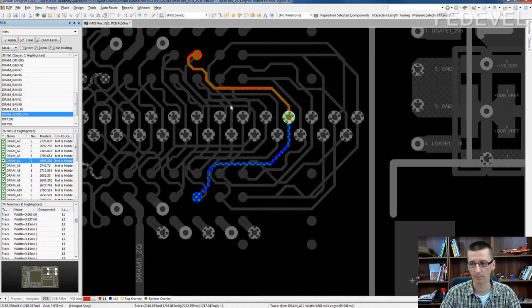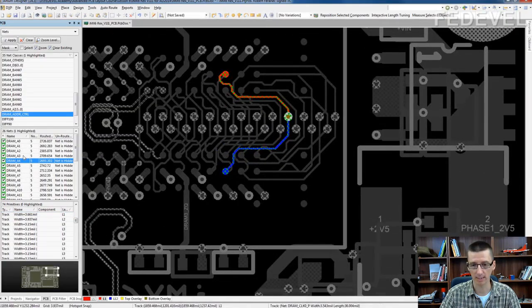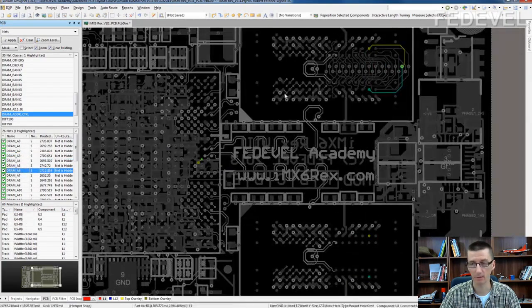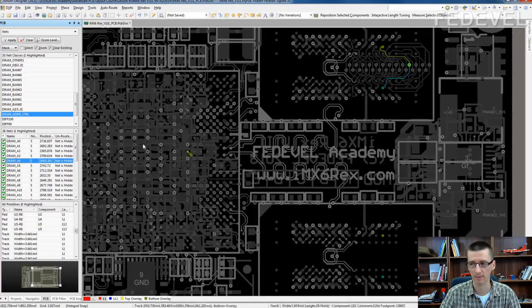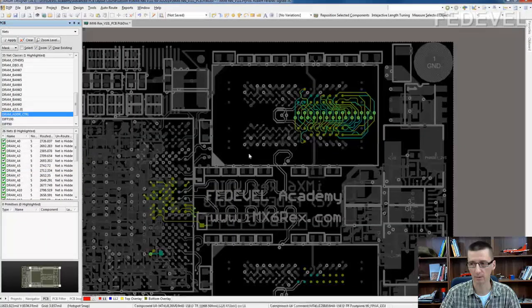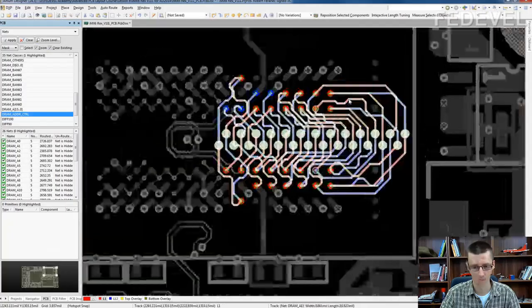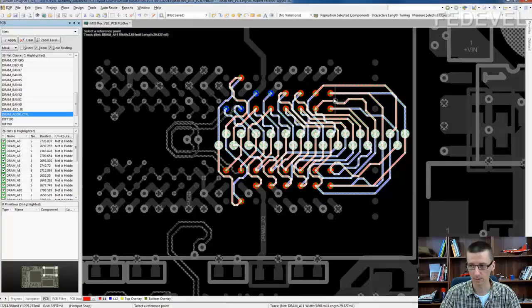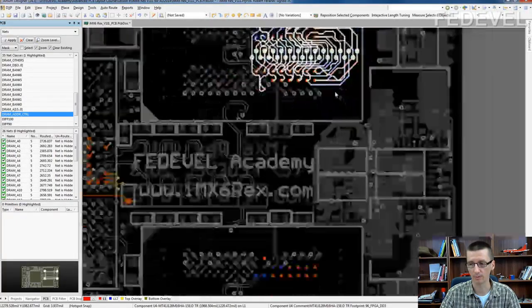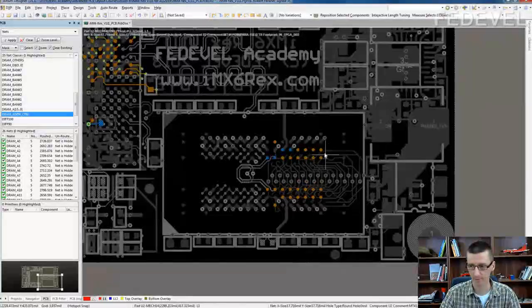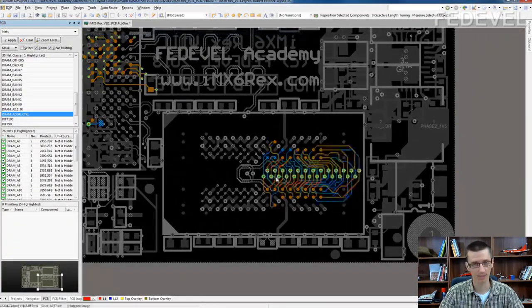Now everything what we have to do when you length match all these signals here, all the last segments, then just click here, copy and paste it, okay? Control C, you already know how to do that. And we just saved a lot of time.